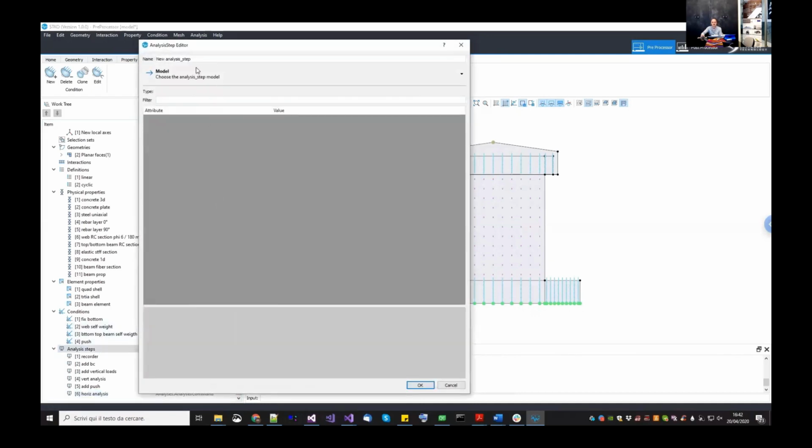Then I add a custom command, which is an adaptive time step. Actually, in a few weeks, this one will be incorporated directly in STKO. But for the sake of this example, I want to show you how to add custom Tcl scripts. Let's call this one adaptive stepping. So we go under miscellaneous command, custom command, Tcl file.